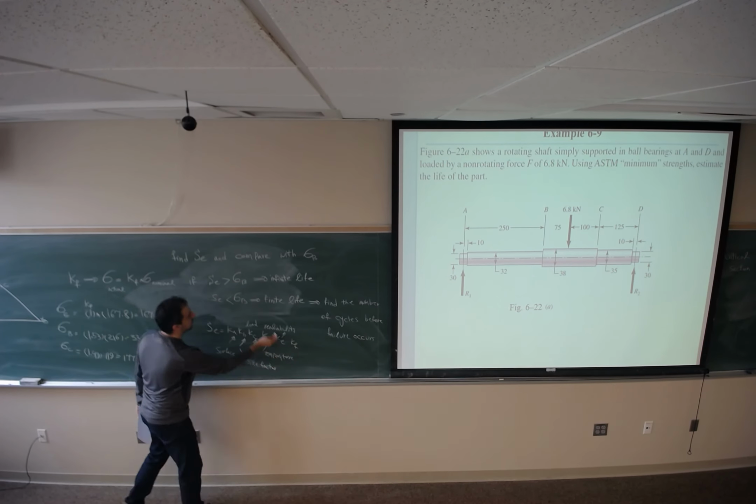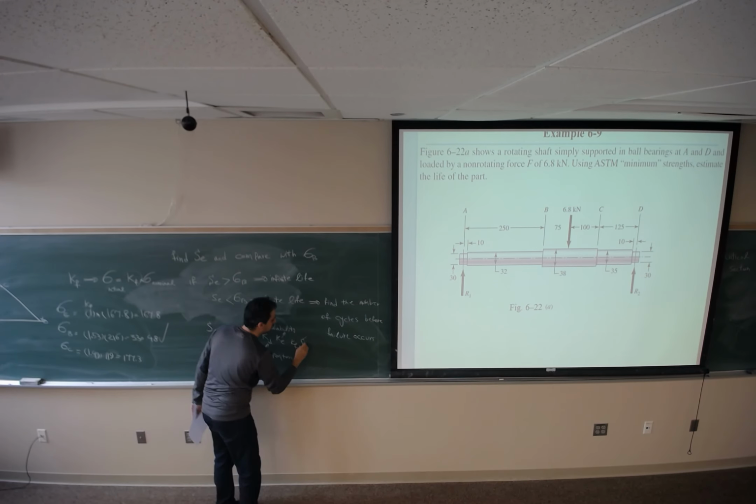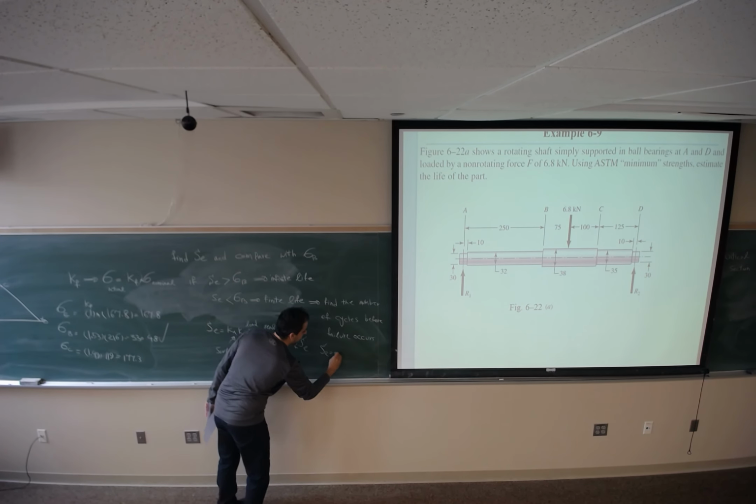This case is different than this. This is the fatigue concentration factor times S'E, and S'E is half of S ultimate.